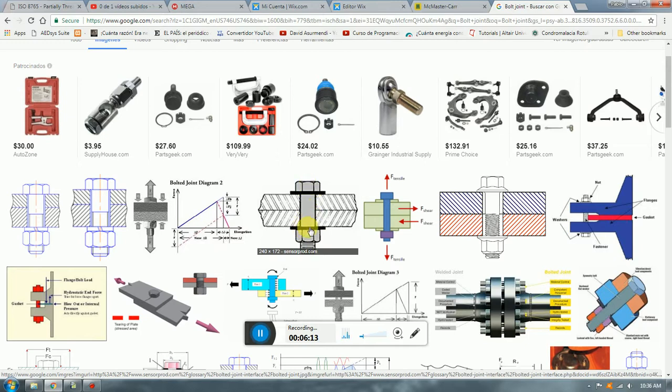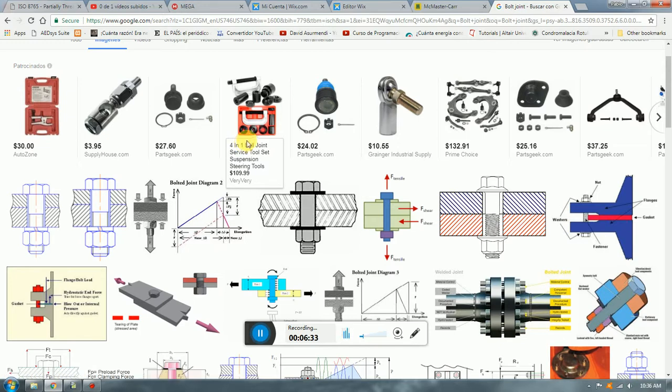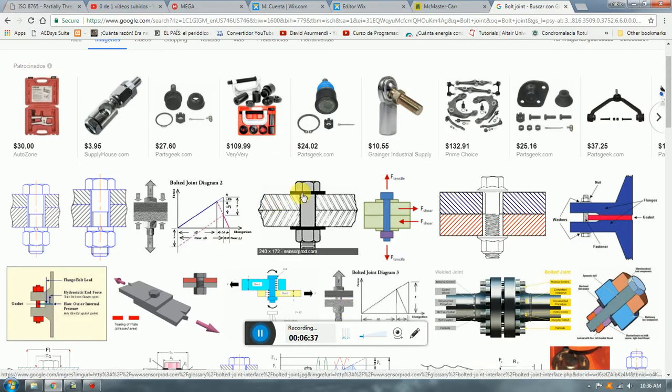And then you're going to get the washers. The washers are not 100% required in all bolt groups. You can see, for example, here is one that only has one, or maybe that one has a specific type of head that includes the washer. So it's not always required. However, in some of the connections, specifically the preloaded ones, they are required. And it is always recommended to put a washer.